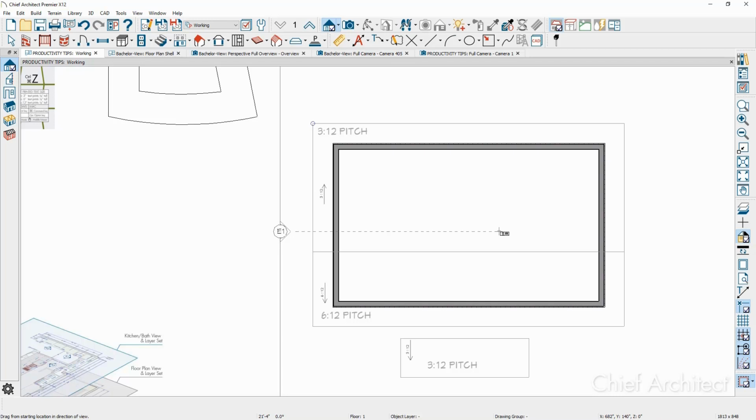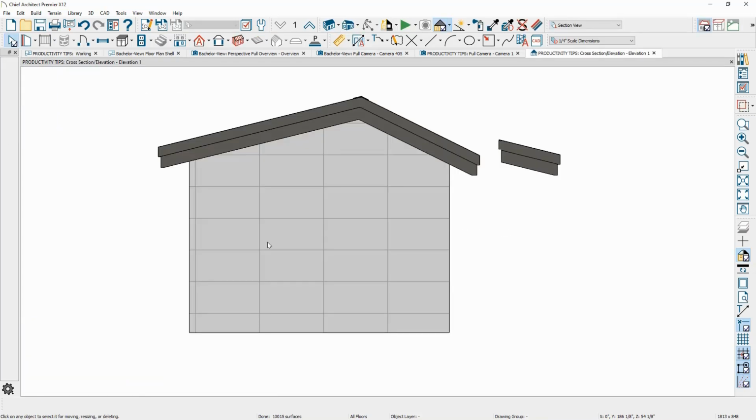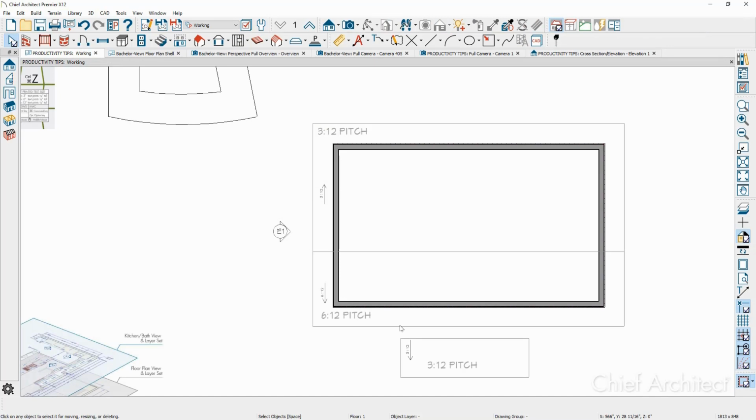If you look at this in an elevation view, let's just shoot an elevation over here. You can see the two different pitched roofs. Using that join tool allows you to figure out where those two items join. This roof plane off to the right hand side might be something for a covered porch. It may be difficult to figure out where exactly that intersects this other roof. Here's what you can do. Let's go back into the floor plan view. This roof plane we want to intersect into this larger roof plane. Here's how we can do that and have the program project where that's going to intersect.